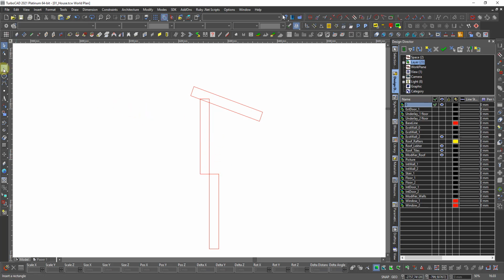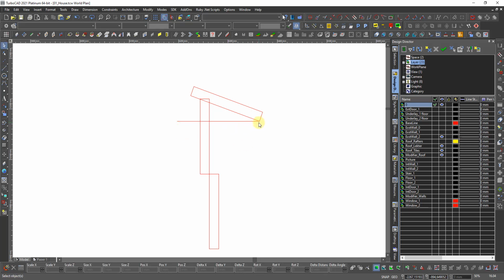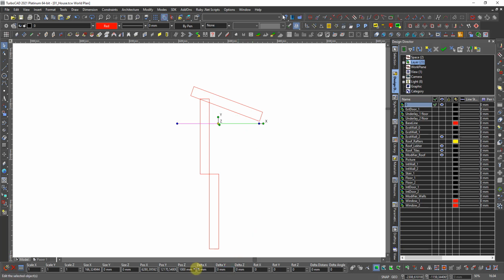And then I want to draw a line. This, you can imagine, should be on the roof. So from B, there. This should touch, or nearly touch. I take this 5 millimeter down, Delta Y minus 5, so it doesn't touch directly. But this is then the reference point here, from the roof tile, when we sweep this.